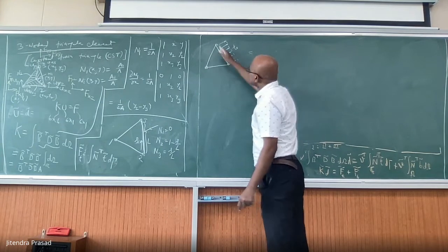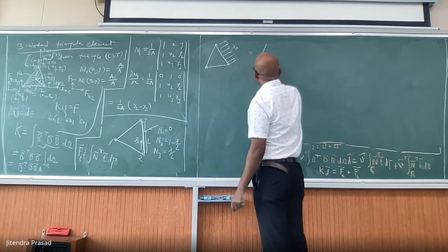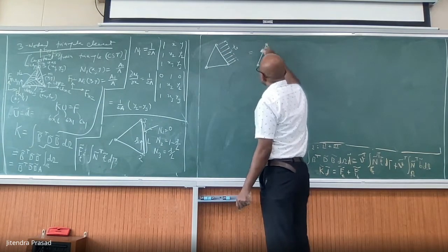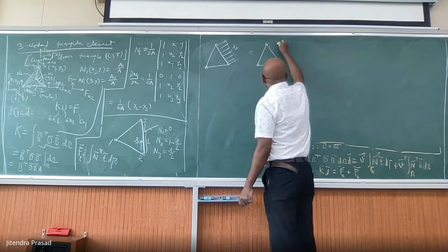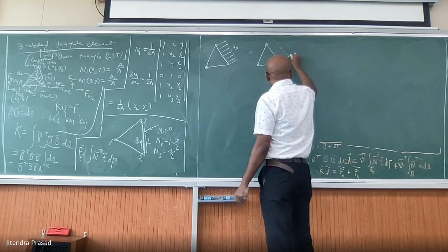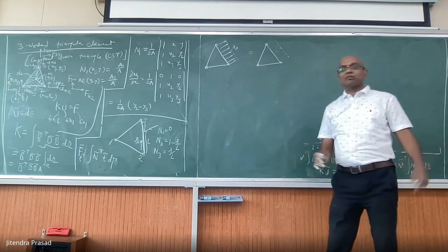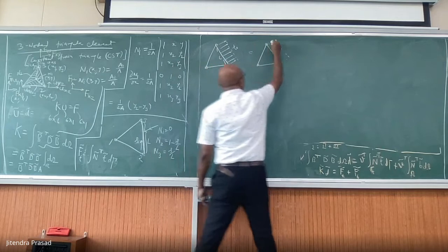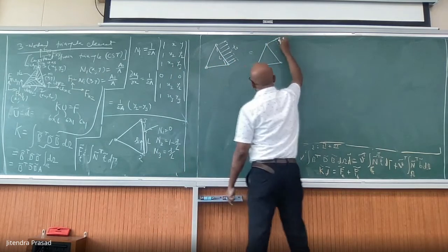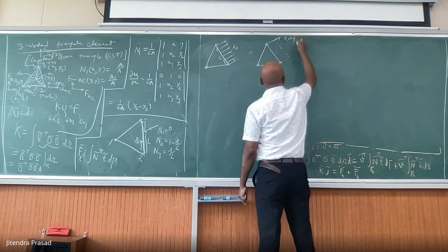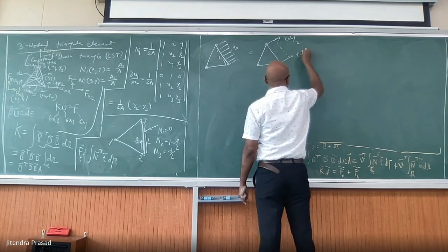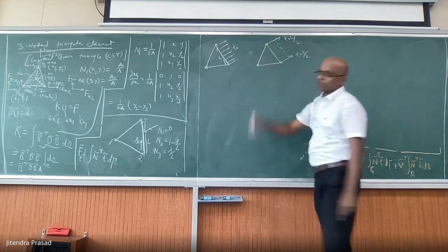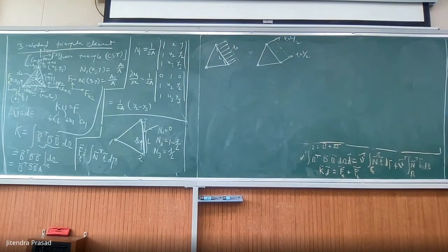This is a continuous system, and we have to convert it into a system which is located on these nodes only. Right? So what will we do? From here to here the length is L, then here it will be T naught L over 2, and here it will be T naught L over 2. That's how it will be done. The same things you have done earlier apply here also.